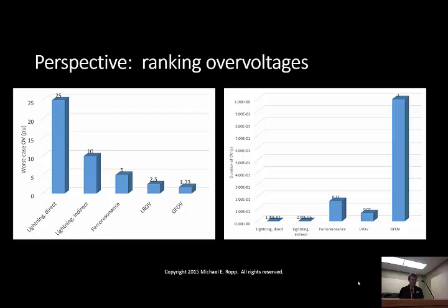And ferroresonance is one of those things that can be kind of scary, because we were examining a case here not too long ago where a fairly large photovoltaic plant had all of its inverters destroyed because of an overvoltage. And we spent some time looking at it to figure out what happened. It was a big plant and had several miles' worth of underground collector system at 34.5 kV because of just the spatial extent of this thing. That was all underground. So 34.5 kV and underground, there was a lot of capacitance in that collector system.